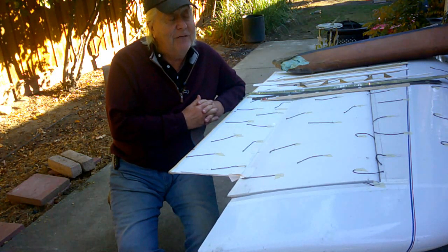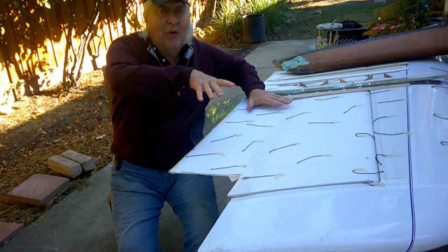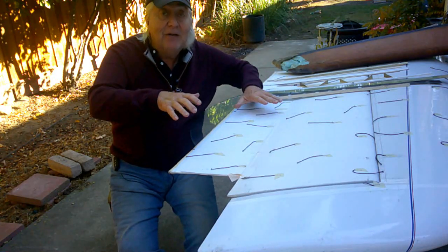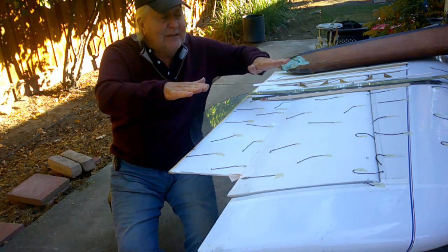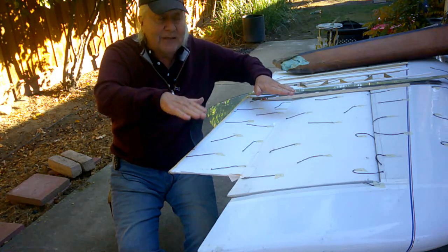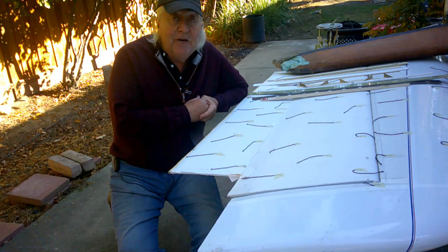What we do with a standard flex wing hang glider is we allow the wing to shift, and we allow one side to billow up more than the other. It's not that we tighten one side down. Well, we do a little bit, but mostly we allow the other side to billow up. It's essentially up and around only, like this. And that's how we turn flex wings. Very efficient.